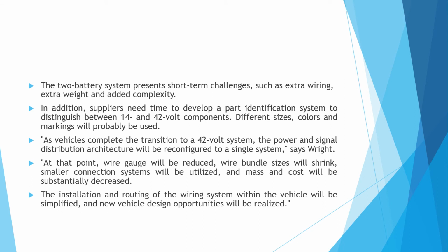The two battery system presents short-term challenges such as extra wiring, extra weight, and added complexity. In addition, suppliers need time to develop a part identification system to distinguish between the 14 and the 42 volt components. Different sizes, colors, and markings will probably be used.